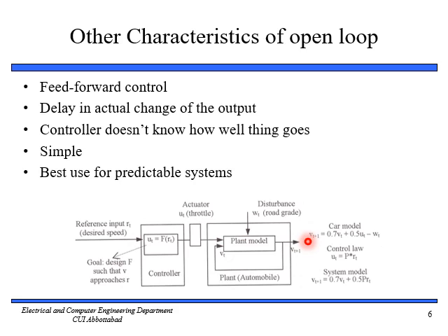The controller reads the reference input. This is the reference input, R of t, and the controller reads it and then computes a setting for the actuator. The actuator modifies the input to the plant. The actuator basically changes the position of the throttle by using a stepper motor, which, along with any disturbance, results sometime later in a change in the plant output.